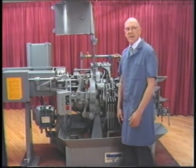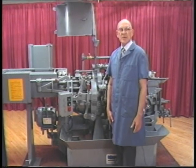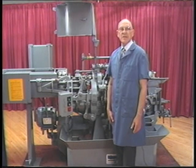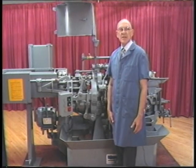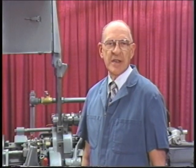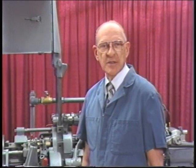Now that you have learned how to stock the Davenport Automatic Screw Machine, you will learn another important function of the operator, tooling. You already know that the stock is held in place by the chuck, which in turn is contained in the work spindle. You have also been introduced to the cross-working tool positions and their 4 front cam levers, and the end-working tools and their 5 right-end cam levers.